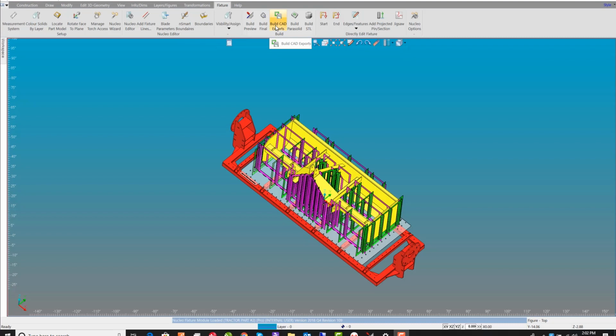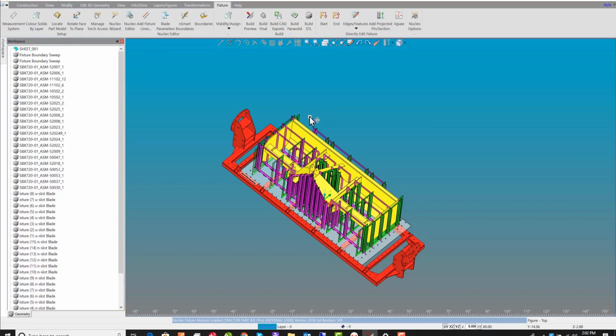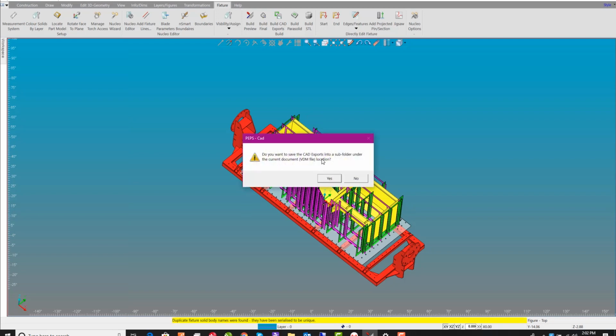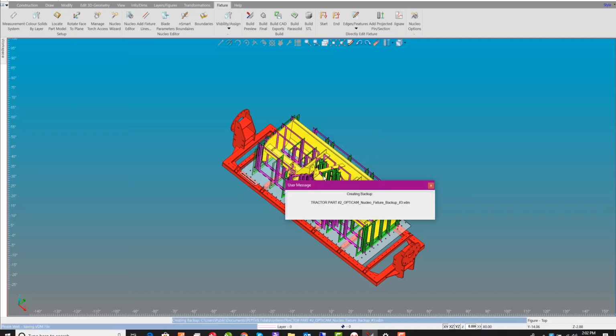Anyway, we can export these CAD files now. We can create a Parasolid and STL automatically, and it will create the DXFs and the bill of materials that we then take to our laser processor, along with some screenshots for the person assembling it. And the STLs are useful for people viewing on the shop floor without a solid CAD system. So you can just use it and look at it in 3 dimensions.